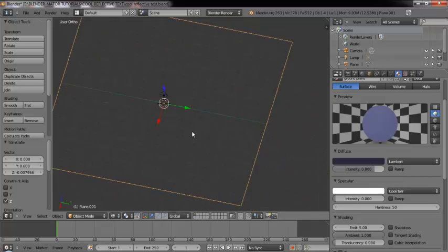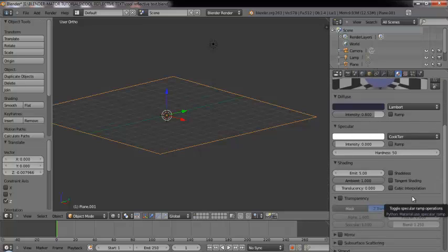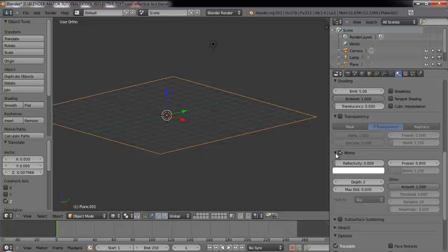Okay, this particular plane is going to be a reflective plane which is going to reflect the text, so we need to add some reflection settings on this. So coming down to this option, click on this mirror option and open the options, and just for the sake, follow the values I give here, but of course you can play around and experiment with other values. So the reflectivity would be 0.5, depth would be somewhere around 5, max distance can be 15, and it just fades to the sky so that it reflects the sky texture which you are going to add in just a moment.